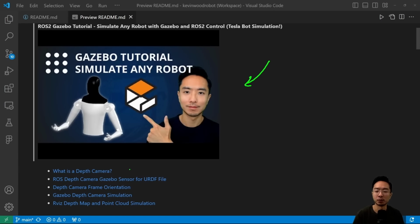I'll be going over what is a depth camera, talk about the ROS depth camera Gazebo sensor setup for your URDF file, talk about the depth camera frame orientation, which can be pretty confusing, and talk about the Gazebo depth camera simulation, and finally show you how to set up everything in Rviz to see your depth map and the point cloud.